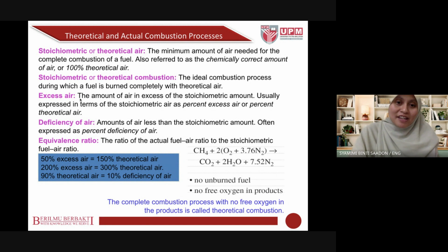And then excess air means the additional, the extra amount of air in excess of the stoichiometric amount. It is usually expressed in terms of the stoichiometric air as percent excess air or percent theoretical air. It means the extra air left after the combustion process. And the deficiency of air: this one is extra, this one is less. And then the equivalence ratio, the fuel-air ratio.